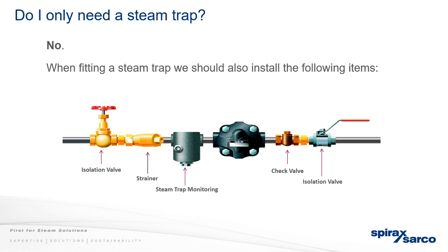But a large enough system, or a system above a certain size, I would suggest you're going to have to pump it some kind of way. The process trapping, as Cornelius said as well, because you've got the FT14 or the flow trap, is allowing for a higher capacity of discharge. So it's near the end of line, effectively end of process, where you're removing the most condensate, and the smaller traps are designed more for the beginning or middle of line, because there won't be so much to clear.